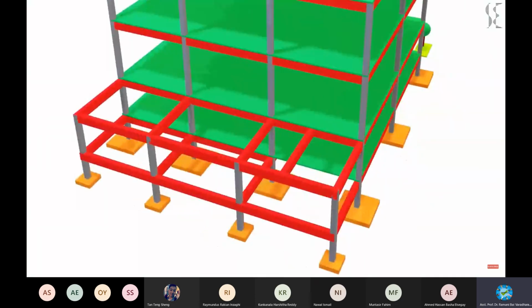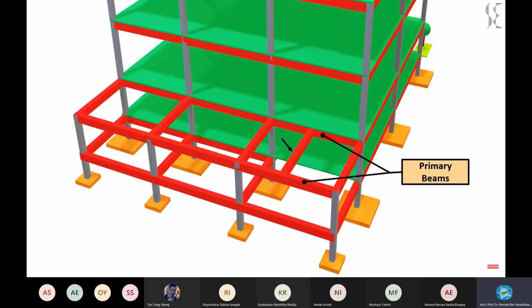Third kind of beams which get torsion forces are the primary beams which support secondary beams resting on them. These beams are main contenders to get the torsional reinforcement due to the loading from one side. Needless to say, these beams require thorough analysis for their design to resist various forces acting on them.